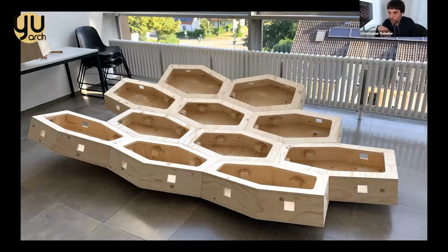So this was the first prototype, and one of the biggest fears that we had was, imagine this as bricks, and in bricks, you usually have mortar, 1 centimeter of mortar, to take the imprecision of your bricks and to compensate for that. And we do not have any mortar in between here. It needs to be perfectly fitting. If it doesn't fit perfectly, you're carrying errors and imprecision into the second row, the third row. We tried to make smaller models of it, but that was impossible because we didn't get the right precision, and then your problems just add up.